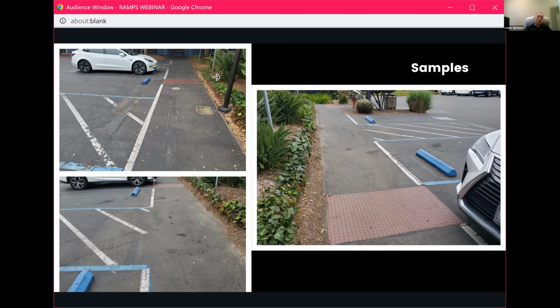So this brings up some interesting concepts for how this would be solved in the new code, considering 11B-250, because 11B-250 limits the design options to only being able to separate the pedestrian area from the vehicular area with a 3-foot strip of detectable warning.